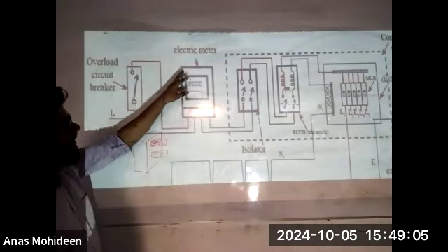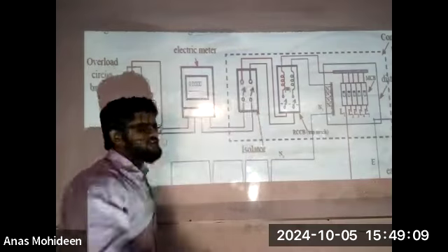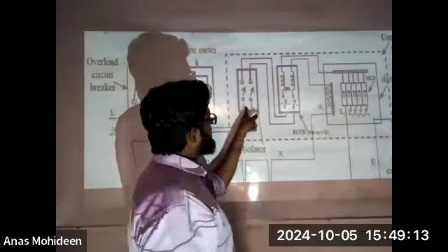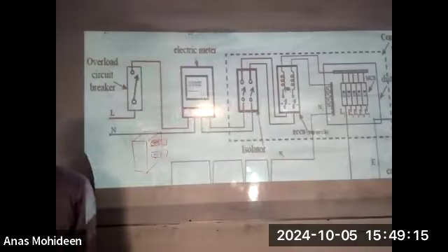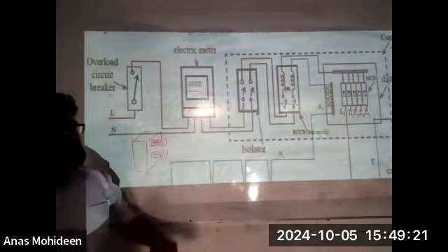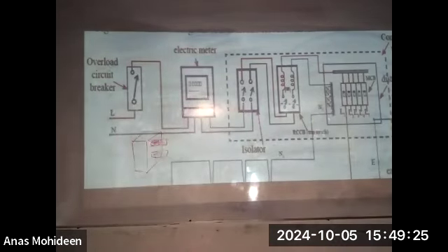Now afterwards, you see both the wires are connected to the isolator, the main switch. When you look at the isolator, there are two switches because two wires are coming. So this is called a dual pole, a dipole switch. What it does is mainly let you control the power supply inside the house. You can control the power supply according to the requirement. If you want to totally take it off, you have to turn it off.